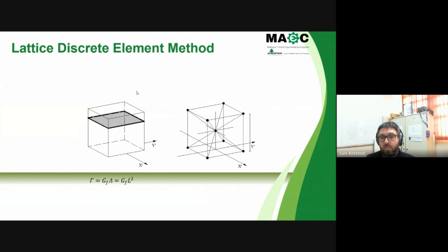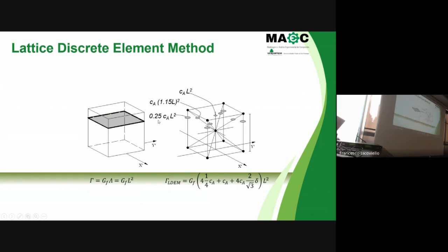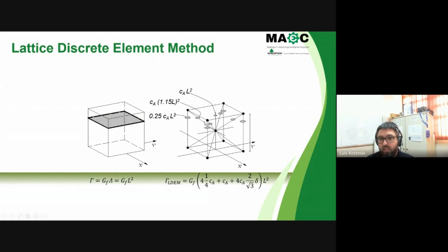For the fracture, consider a cubic solid that is cut in 2 parts. The energy released in this cut must be the same as the energy released when we cut a basic cubic module. Then we calculate the fracture area needed to have exactly the same energy in the two cases. This fracture area is utilized also in the element. Then every element has 2 areas, one area related to the fracture and another area related to the elastic properties.